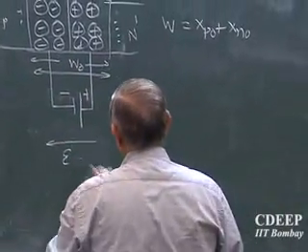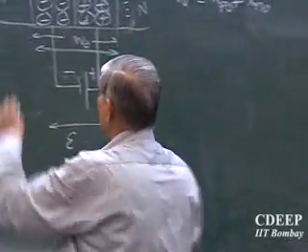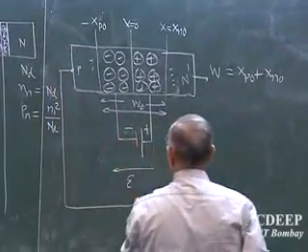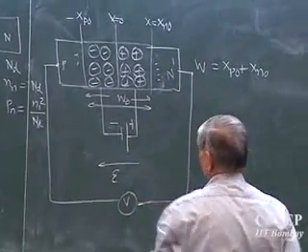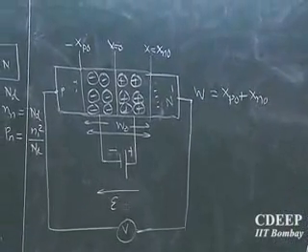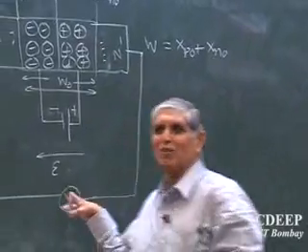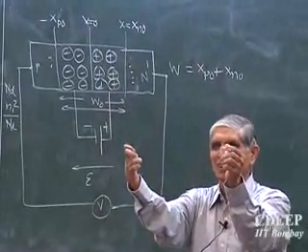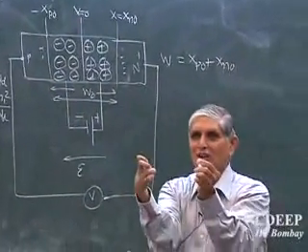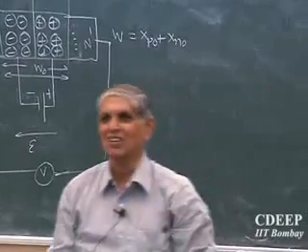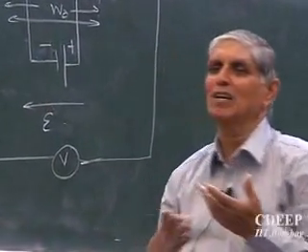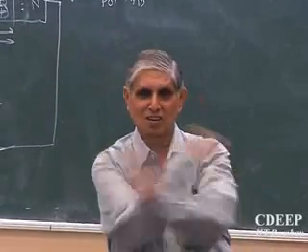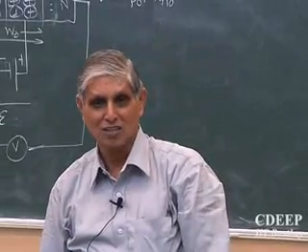Before we go ahead, I already said there is no voltage drop here or here, but let's say I make a contact here. If I apply a voltmeter across this, would you see a deflection? I repeat, the problem is this. Is that clear to you? I have created a battery, so if I apply two terminals, of course there is no drop here anyway. So if I measure across this, I should have seen V, but I don't see any deflection. So that means this battery is some kind of quasi or false battery sitting there. But if it were not there, this would really have gone infinite. All holes and electrons would have diffused out. That has not occurred. Obviously there is a built-in field.